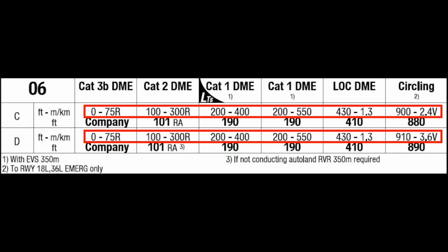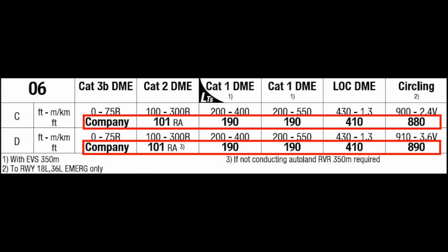Heights and ceilings are shown together with the vertical sight requirements. Ceiling values are prefixed with C, measured RVR as a suffix of R, and visibility that cannot be converted is suffixed by V. The operation line provides information about the applicable minimum value. The values stated here are the governing basis for decision making. It shows minimum descent altitude for non-precision approaches, decision altitude for Cat 1 approaches, and radar altitude values for Cat 2 or Cat 3 approaches respectively.